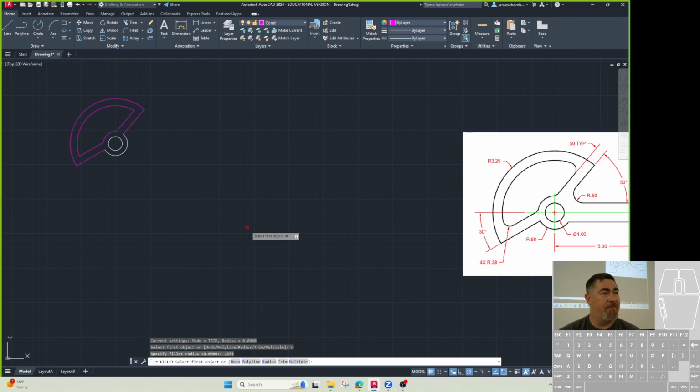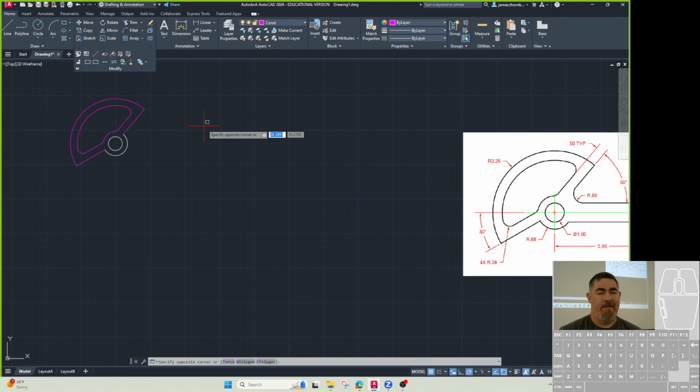Multiple. There's an option called Polyline. I wonder what that does. It's a polyline. So if I go to Polyline and I pick this, all of the corners on the polyline get changed to fillets at the same time. I don't have to pick each corner one at a time. But they all have to be joined together into a continuous polyline. So the join command lets you do that with one command.